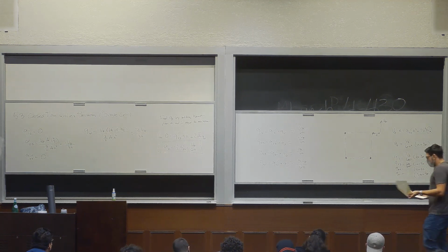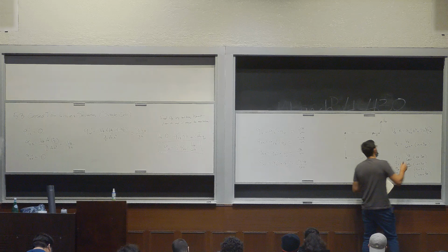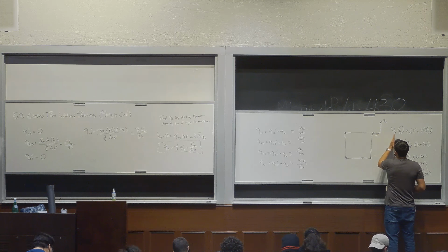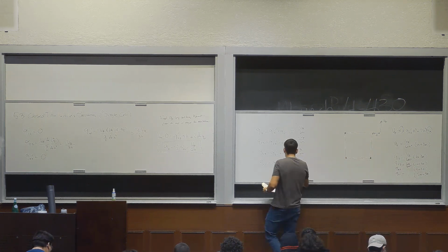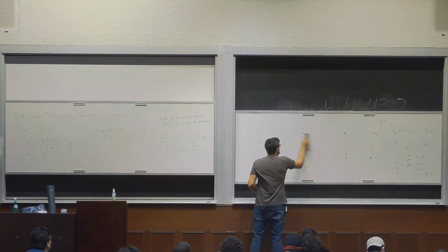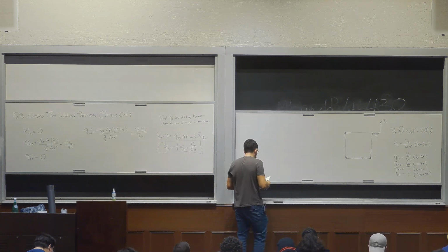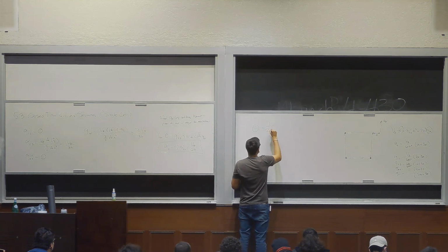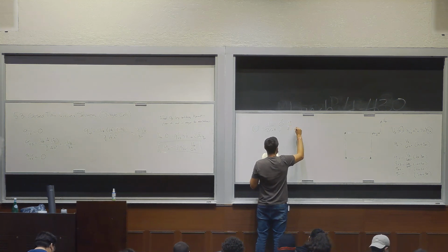And now, the way we solve for that variable E, right? They're asking about the shear center. All we're interested in is finding that E. We'll get a value for it; if positive, then we know the distance from that original point. If it's negative, then it's in this direction. And the equation that we use is the rate of twist equation. If you remember how to find theta, from the torsion chapter, theta is 1 over 2 GA line integral Q over T ds.